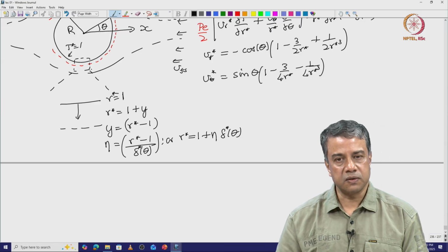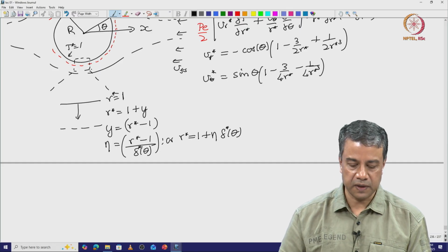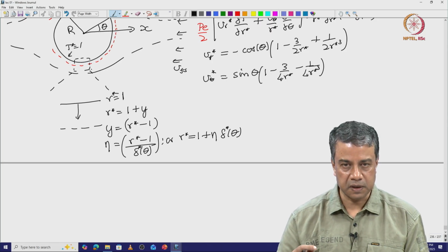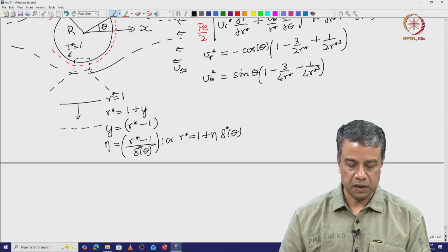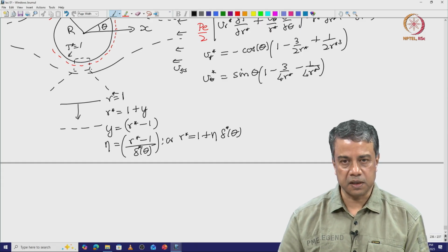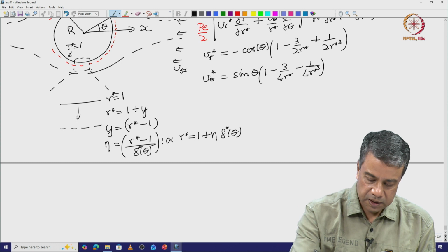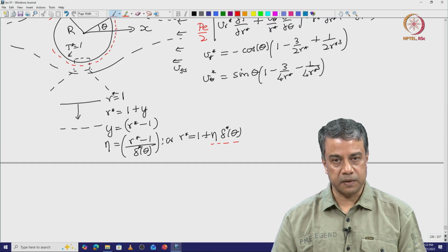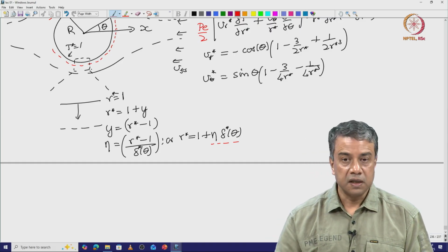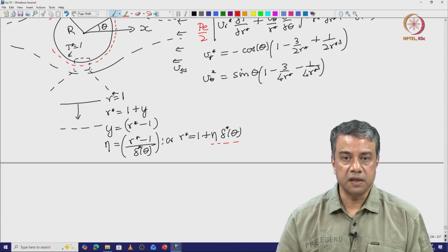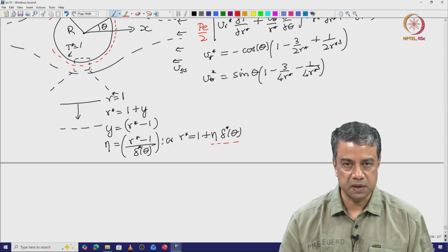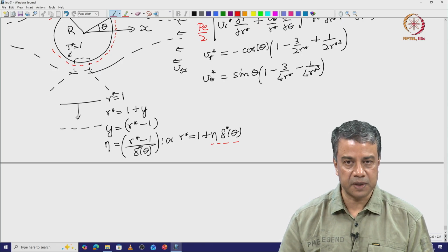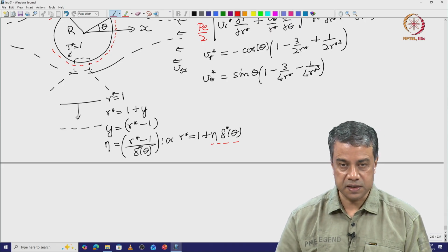I have to substitute this into the equations and into the velocities in order to find the convection diffusion equation in terms of the similarity variable eta, and the velocity components in terms of the similarity variable eta. Note that in this expression, eta is order 1. It is a scaled similarity variable. Delta is the boundary layer thickness. It decreases to 0 in the limit as Peclet number becomes large, so that convection and diffusion are comparable within the boundary layer. So, delta is the parameter that goes to 0, and eta is order 1, a scaled variable.